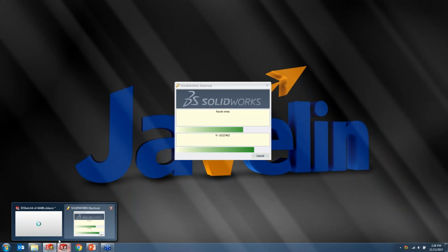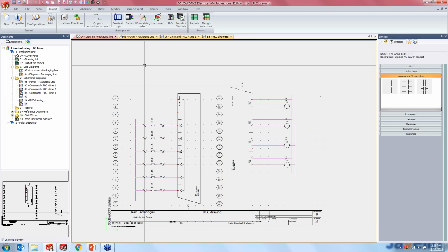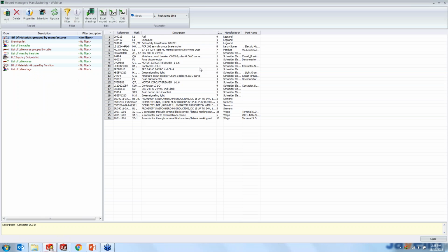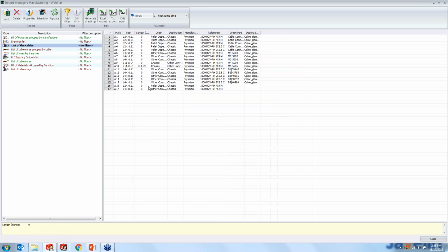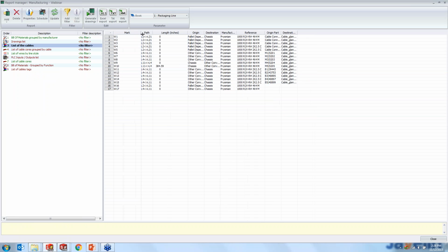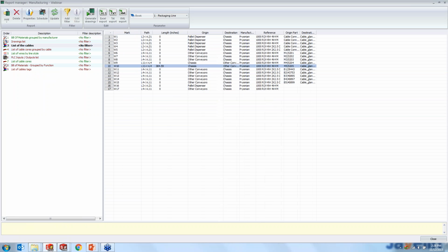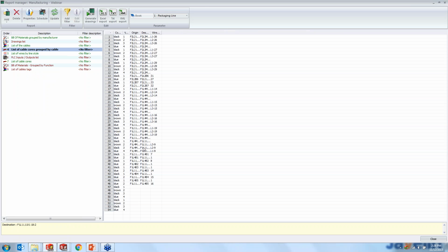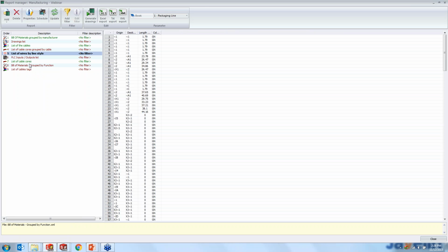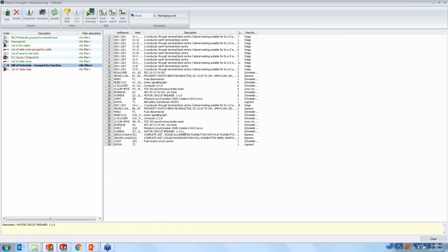And the manufacturing documentation is essentially your reports, which are automatically done. As soon as I'm looking at the reports, they're automatically done. We added a motor M5 that's already here. We can create cables. We routed the cable W10 between the motor and the other conveyor section, M5 and the cable gland, and it'll give me the length. So it already knows what the length is. It knows every cable that's in here.